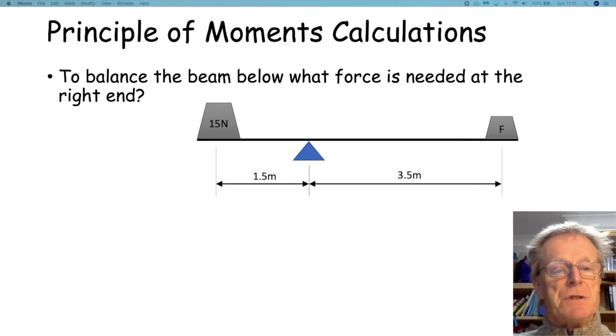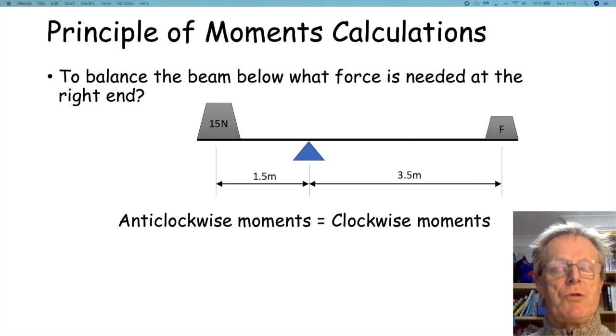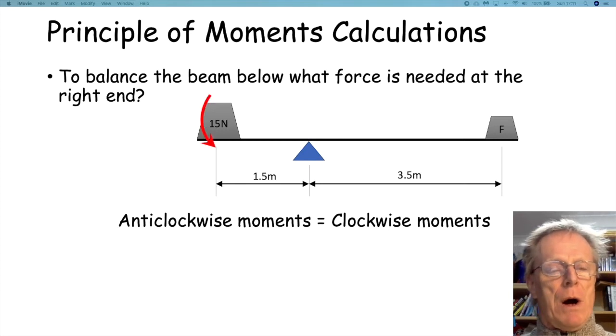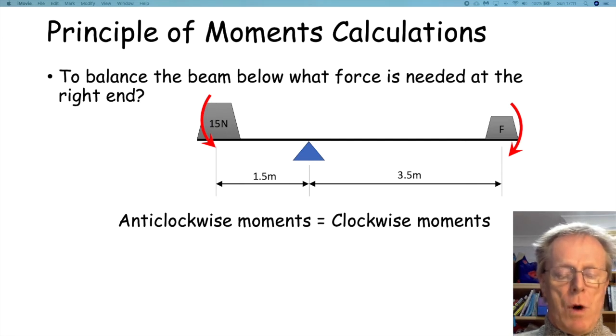So the first thing to do is just write down your statement of the principle of moments, which is anti-clockwise moments equals clockwise moments. And then you can start putting the numbers in. So all the things that are trying to turn it anti-clockwise, I'll put a little arrow in here just to make it a bit clearer. That's trying to turn it anti-clockwise, the 15 Newton load. So therefore, on the other side where the unknown force is, which is trying to turn it clockwise.